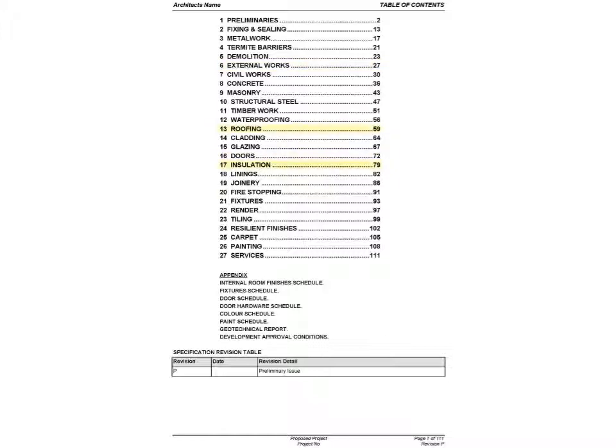A drawback to specifying, say, an insulation product in roofing is that we need to first include all the insulation backup detail and repeat this detail everywhere an insulation product is specified. It is better to specify things in one place only. Element-based spec sections, say partitions, are inefficient also, as partitions have masonry, concrete, linings, tiles, resilient finishes, waterproofing, glass, metal, timber framing, metal framing, skirtings, cornices, painting, and electrical and hydraulic services. Then, spec consistency would require a roof section and a floors section, and the range of possible materials and detail repetition becomes unmanageable.